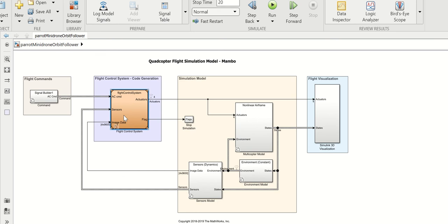So your main thing at the moment is to be able to load in the simulation, run the simulation, go into here, change the PID gains on height and yaw, and get some transient responses out. And what you should see is your classical type responses. More proportional speeds it up, more derivative adds in damping. You don't probably need much I at all. So it's mostly PD control you're looking at, and you can then investigate different PD designs using the simulation. And if you can get all that to work, then you're well on with the project.